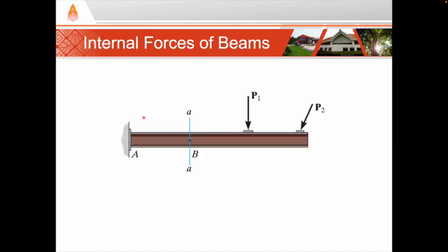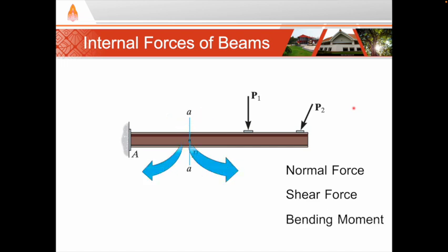When a beam has forces applied to it, there are reaction forces inside the beam at every point. There are forces perpendicular to the beam's cross-section, which we call the normal force. There are forces tangent to the cross-section, which we call the shear force. And there are bending moments.